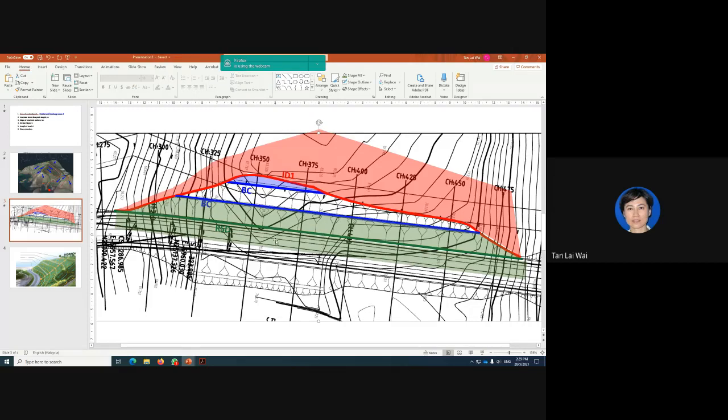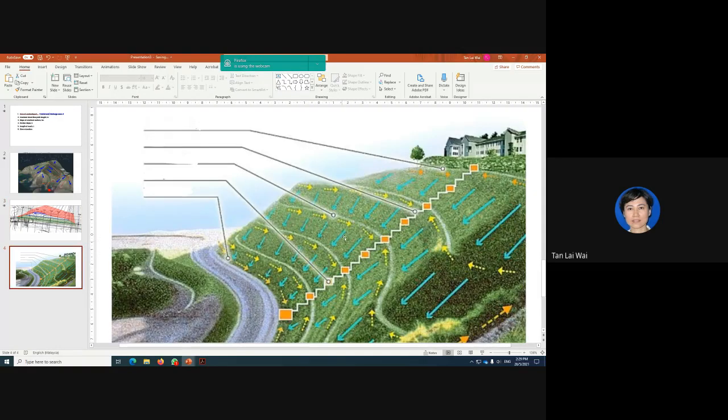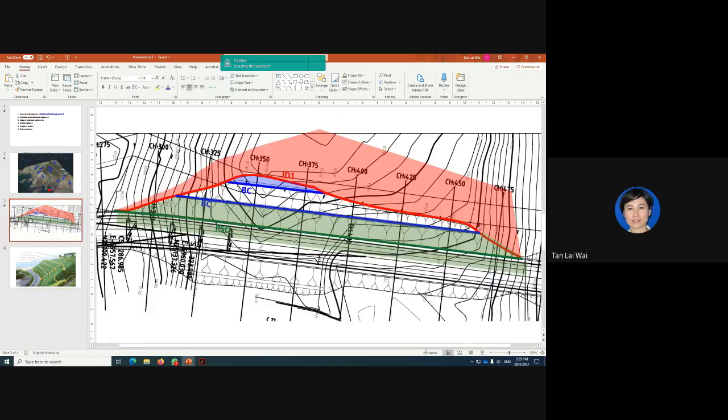But remember, this is only half of the road, and the land use coefficient for the road is different from the land use coefficient here, because here you consider turf, the cut is turfed, you have grass cover, whereas the road cover would be pavement. So it's different. I think it's 0.95 for the road, and this is maybe 0.55 or 0.6. So given the same area, the road would have larger Q compared to this, but you have to combine them in order to design the roadside drain.